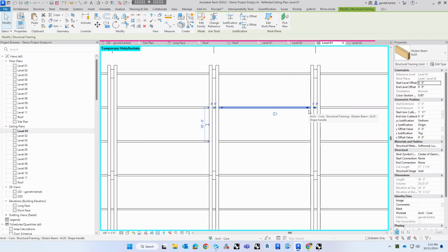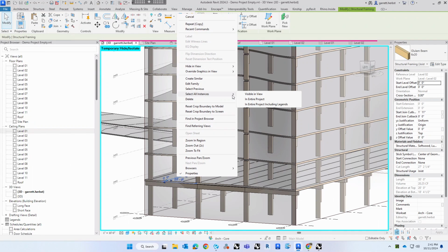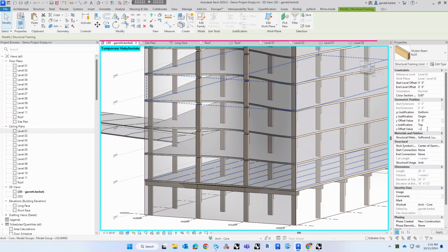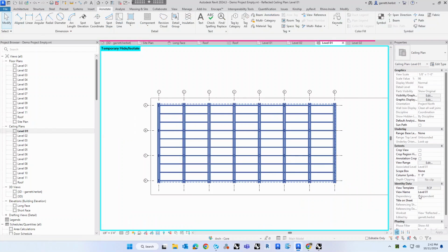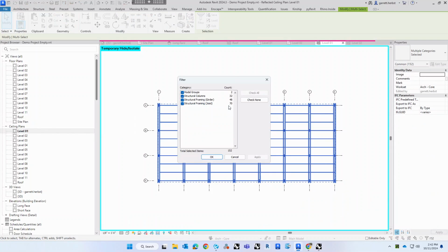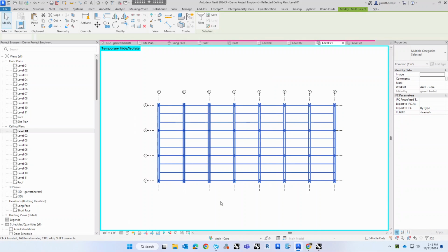Okay, so the other thing is I have to change the Z offset so that they're sitting underneath the slab. So again, Z offset, negative, whatever your depth is. All right, so I always validate what I'm doing in 3 dimensions. That is one of the big benefits of Revit, being able to visualize what you're drawing in 3 dimensions in real time. A lot of people will constantly run into issues and not be able to figure it out. And every time I just go into the 3D view and it's glaring them in the face.